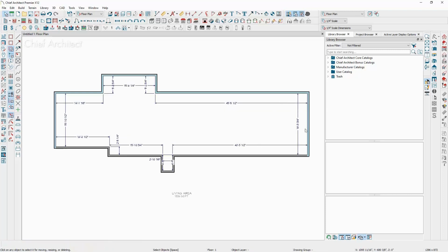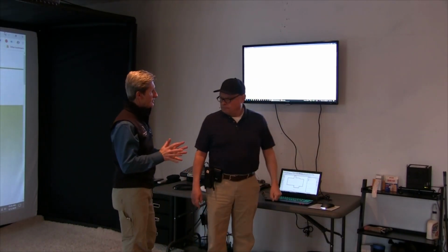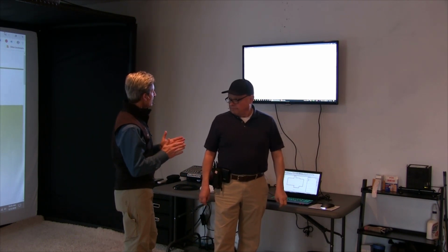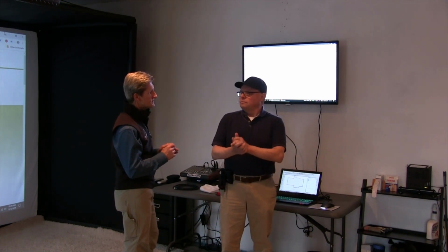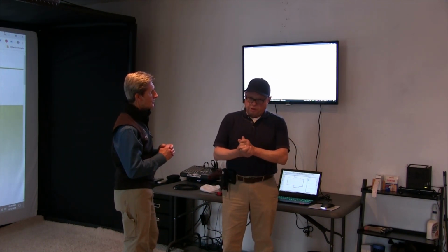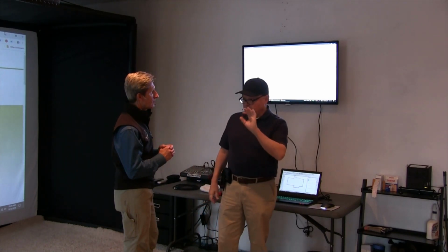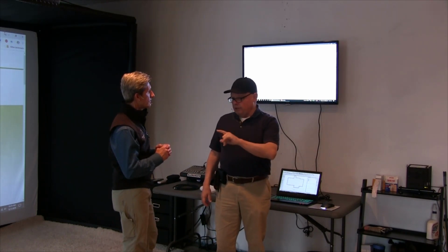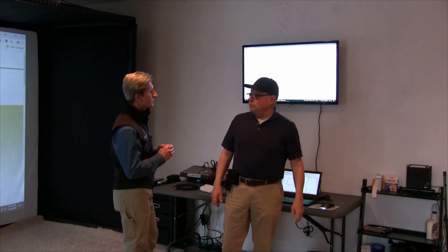And the other thing is, if something is dimensioned, I usually like to get it correct right off the bat. So when you do your dimensioning, this tool, the automatic interior dimensions, places the dimensions. You are a little more picky about that, and you're very proficient at your dimensioning, so you'll run those manually. I'll run the dimensions manually. The reason is, when the dimension goes in is when it's actually set. If I see a dimension that's there, I might assume it's already been set, and it'll introduce an error into the process.